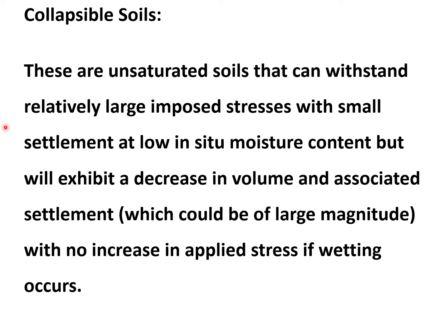So please go through this statement again. These are unsaturated soils that can withstand relatively large imposed stresses with small settlement at low in-situ moisture content, but will exhibit a decrease in volume and associated settlement which could be of large magnitude with no increase in applied stress if wetting occurs.